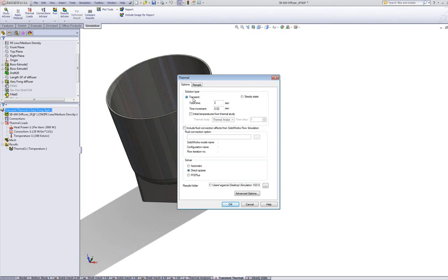Now below that, you get an opportunity to select your time domain, or your overall study length, and the time step for your model. Again, the finer the time step, the more resolution you get for your results, but the longer it will take to run. In this case, I'm going to do a 0.02 second step for a total of 2 seconds. My setup for this simulation is going to apply one cycle of flash to this model to see what's going to happen to my temperature.